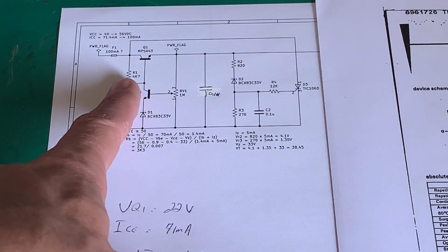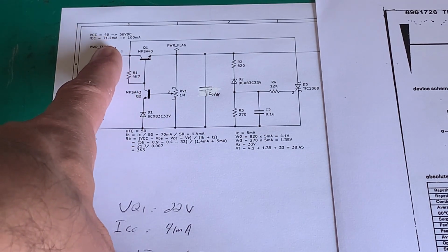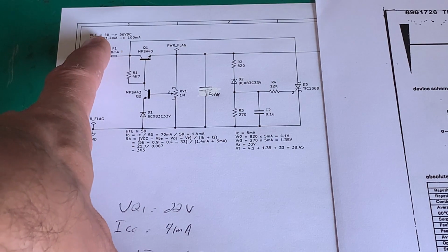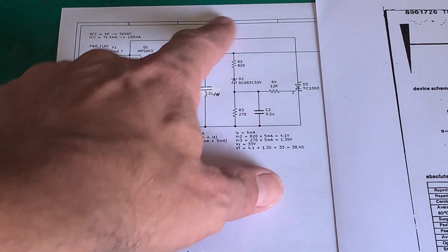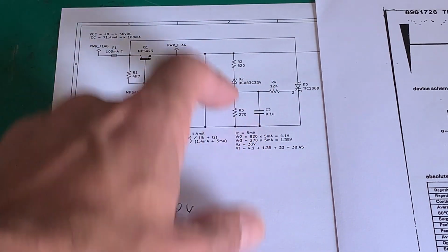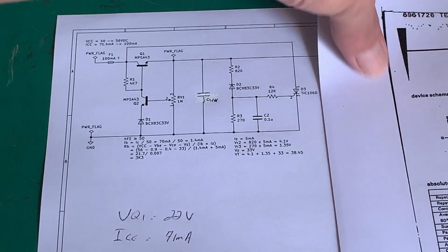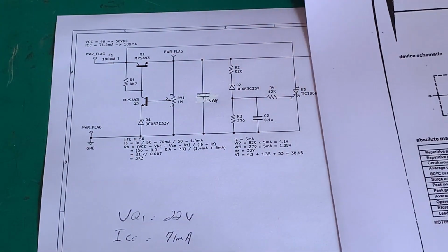So by monitoring this battery level, ideally we'll do that later on, but obviously I don't want to take mains power, I want to take it off the battery bank, so that's why we've got between 40 and 56 volts. I can regulate my voltage, I can create some protection for that, for overvoltage, and later on we're going to go to switching regulators and things like that.